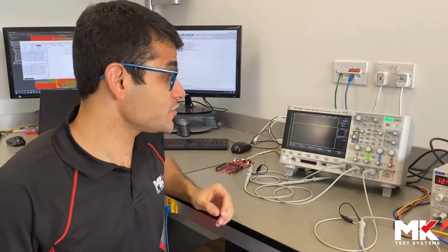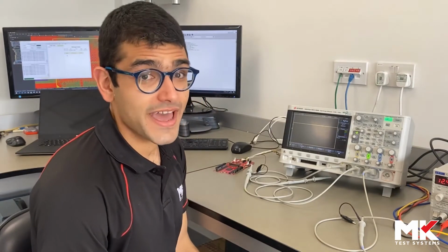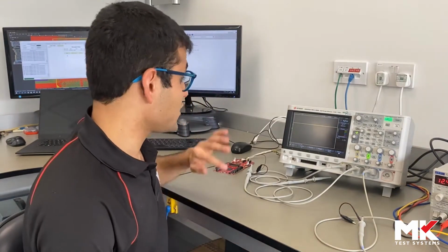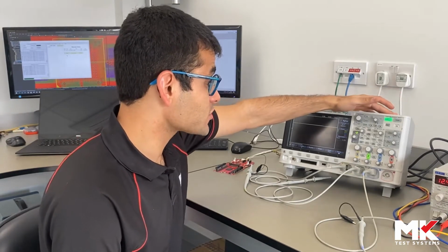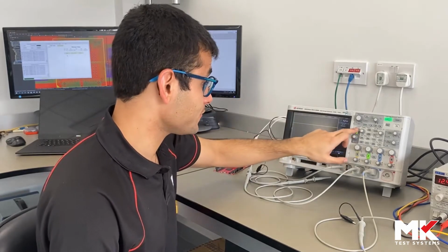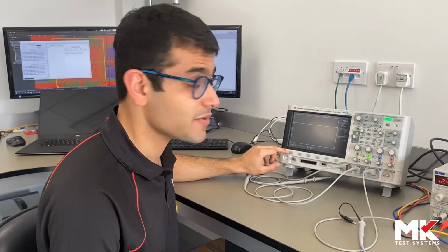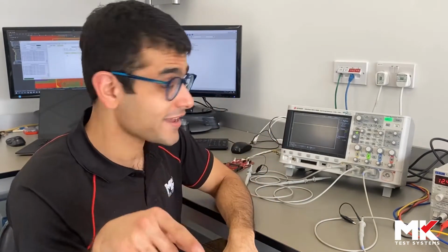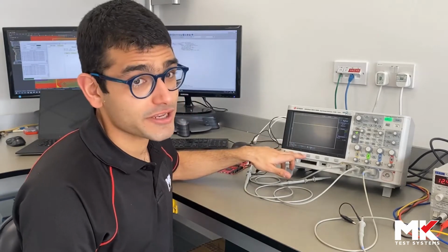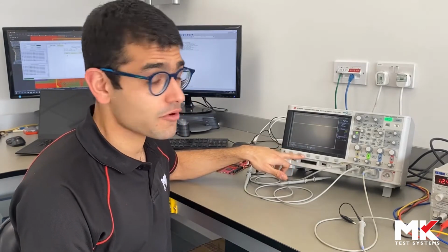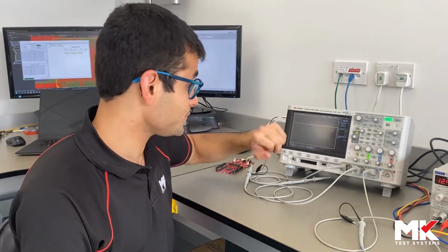So the tip here is to learn to trigger the scope in order to catch signals. How I've done it, I have the PC set up ready to send signals to the board. But speaking of the scope itself, you need to go to trigger and select the edge you want to trigger on. In our case, it's going to be a falling edge because, as you all know, the UART start bit starts with a falling edge. Choose the correct channel, because I always get tricked into choosing the wrong channel. In our case, it's channel 2.